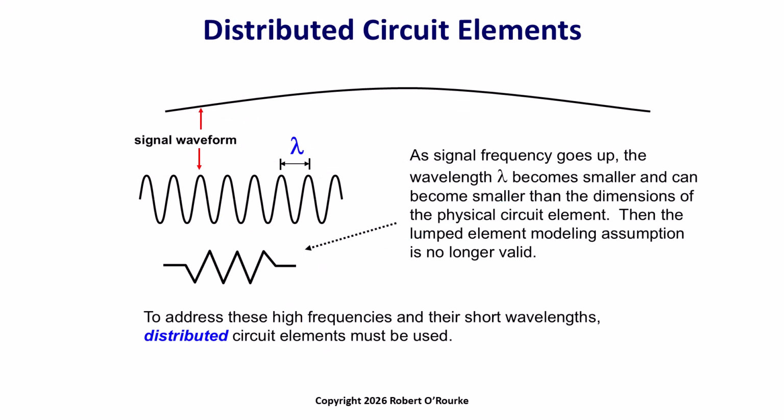At higher frequencies, shown by the sine wave in the middle, the wavelength becomes small relative to the physical size of the circuit elements. We have also answered a different question. How high in frequency are lumped elements valid? The answer is that it depends upon the physical dimensions of the circuit.